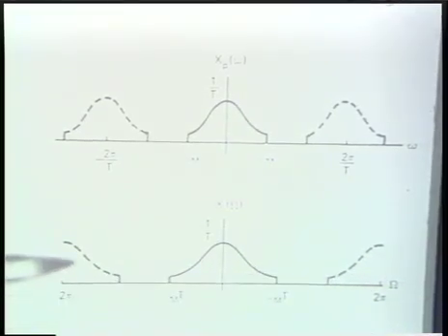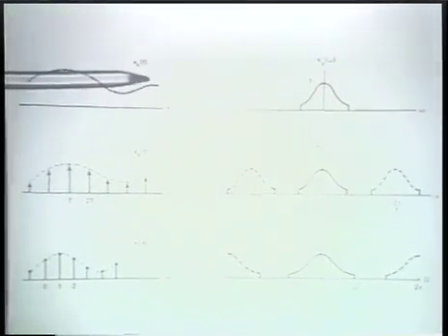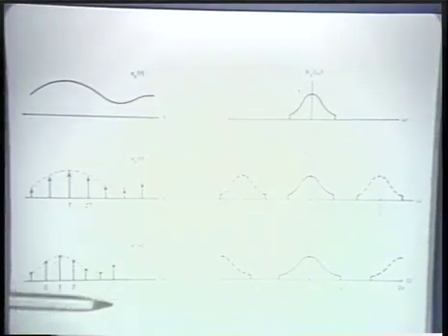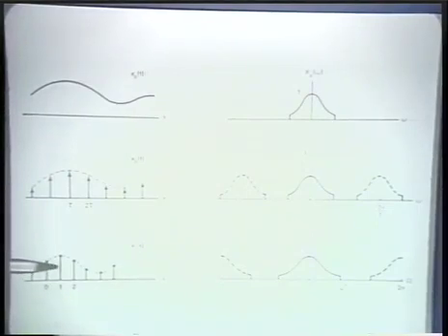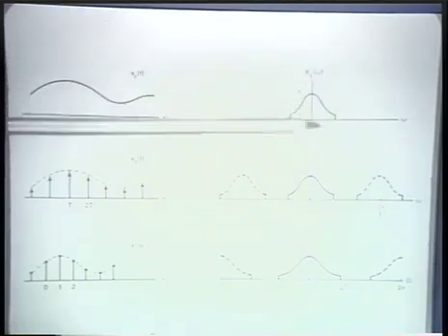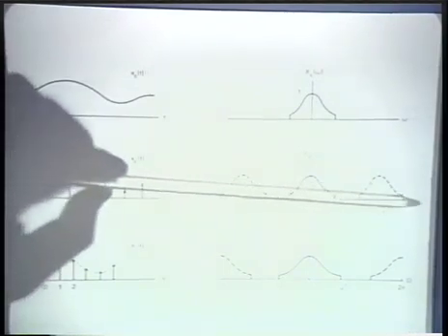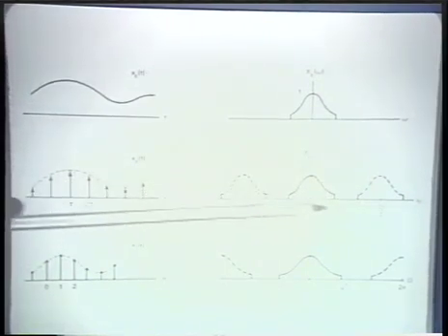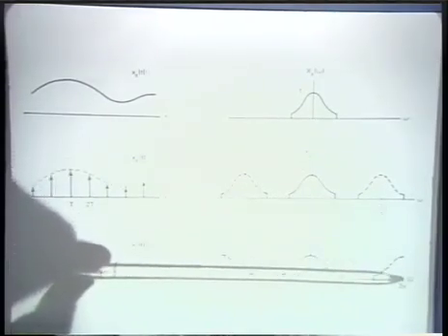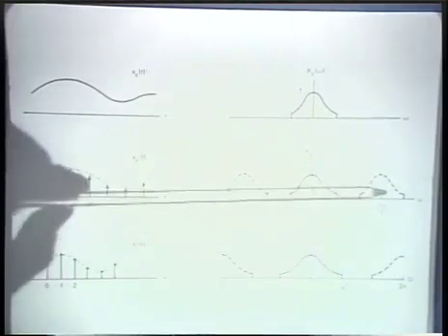So just looking at this again, and perhaps with the overall picture, in the time domain, we've gone from a continuous curve to samples, relabeled those, and in effect implemented a time normalization. Correspondingly, in the frequency domain, we have replicated the spectrum through the initial sampling process and then rescaled the frequency axis so that now this periodicity corresponds to a periodicity here which is 2 pi and here which is the sampling frequency.